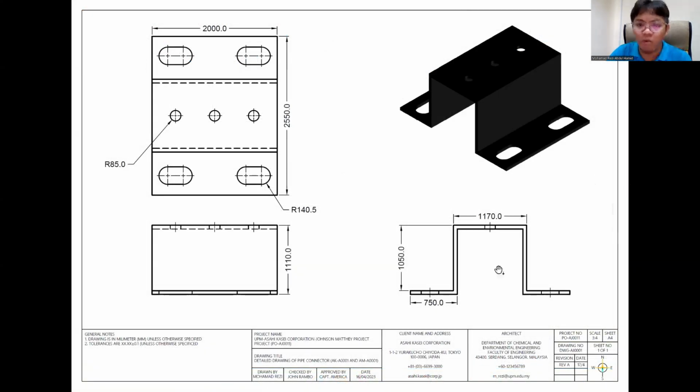Okay, as you can see, this is my drawing, so all looks nice. But again, what I don't like about Viewbase is that the line types they use are the same line thickness. It should be different. Your object line and visible line should have a thicker line. Your hidden line and center line have a different thickness as well. So you have to make sure that these are all dash lines. You should change this to a better dash line, but for this demo, I don't have enough time. But you should.